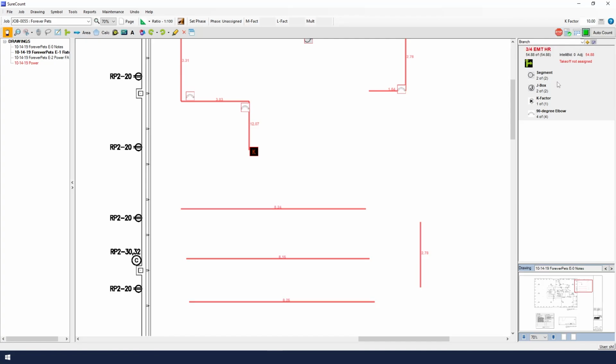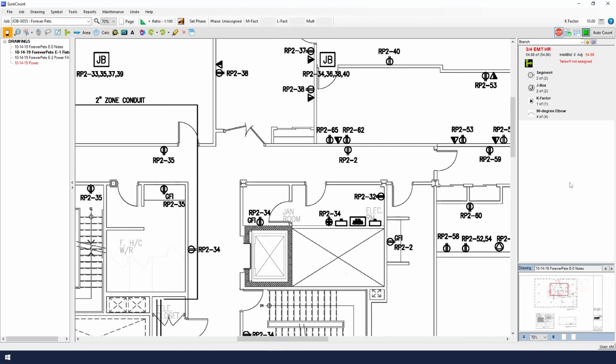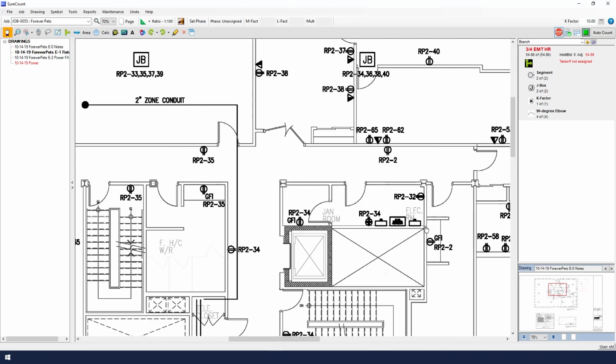Now we'll apply the things we learned to the drawing itself. First, we'll scroll over to get onto the middle of our drawing. We will perform a measurement from the electrical closet up and then across to the left. To make that happen, we click our symbol to get in measuring mode. We click our first measurement. We will press and hold down the Shift key, and then click up here, and then click over here.